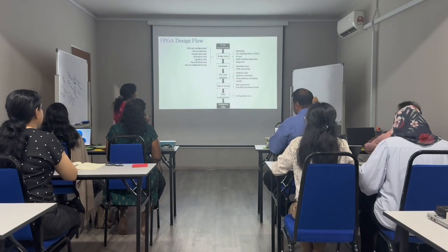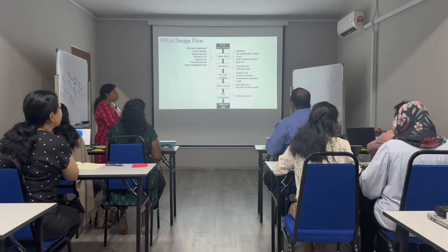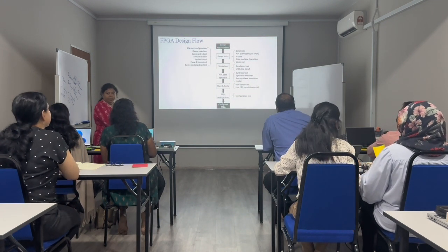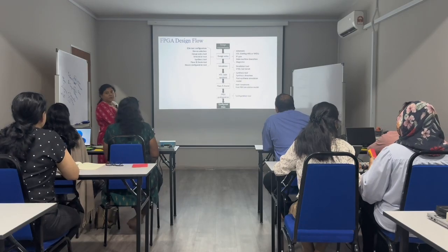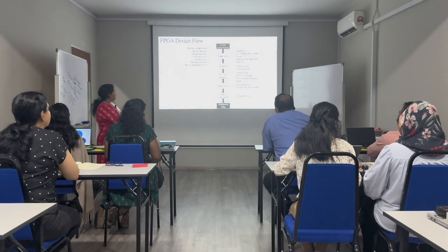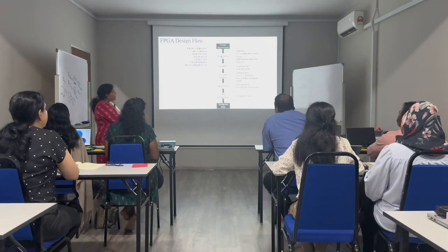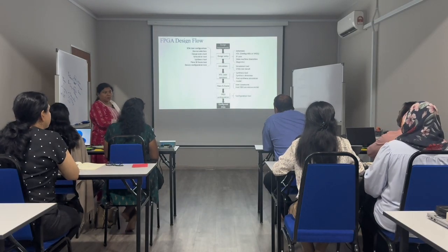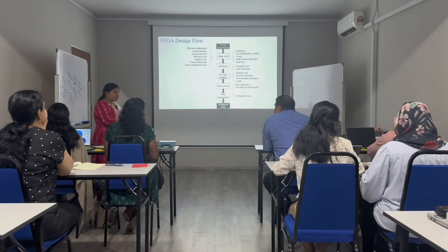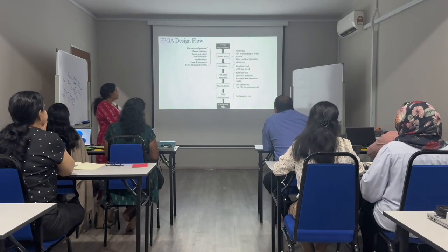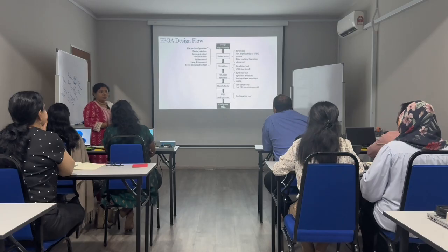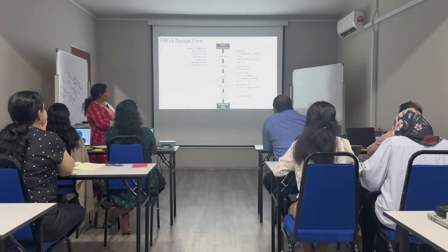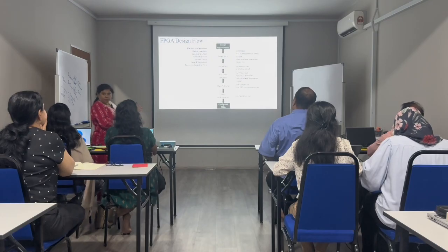Architectural plan. So that is called the design requirement. So what design are we going to design? What are the inputs? What are the components requirement? Everything will be decided at this phase. Once this is done, we will go for design entry. This is the application development side where we will use VHDL or Verilog. Those languages will be used to enter our application.